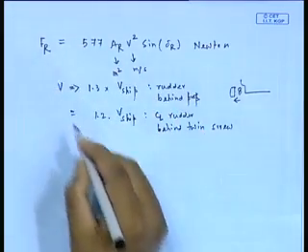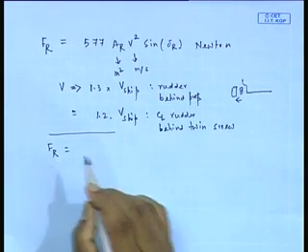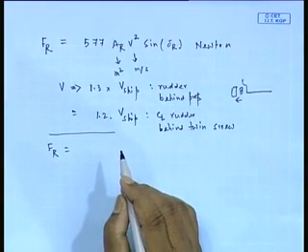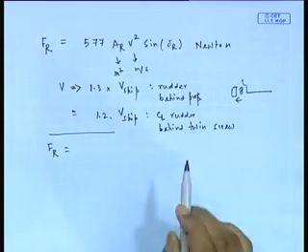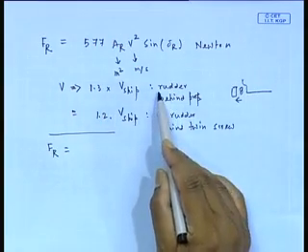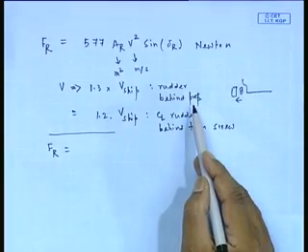Another formula. No, it's true. This is why I said rudders behind propeller. It can be single screw, twin screw, as long as you have the rudder behind the propeller. But there are ships where the rudder is not behind the propeller, they are twin screw but centerline rudder.